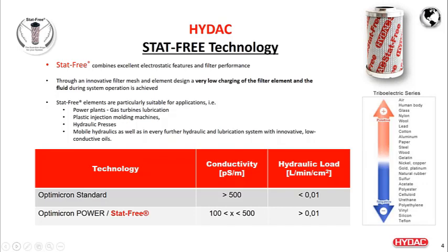And because of this charge separation or charge generation, electrostatic discharge occurs anywhere in the downstream of the filter. In order to avoid that, we need to select the material of the filter element that is close to the oil, and behaves or works very close to the oil electron work function. So HYDAC understood this phenomenon back in the 2000 timeframe and developed stat-free technology. So what is stat-free technology?